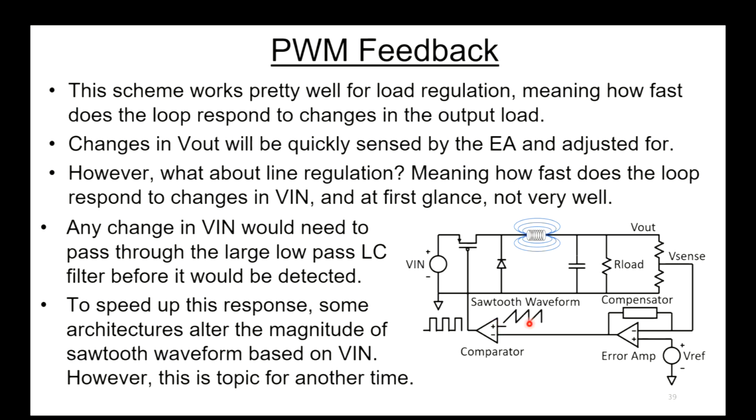This is a pretty common technique used to improve the line regulation, and you already have pretty good load regulation. Now there's yet a third one that I'm really not going to talk about here, where you measure the peak current through the inductor, and I'll briefly talk about that when we get to boost converters.